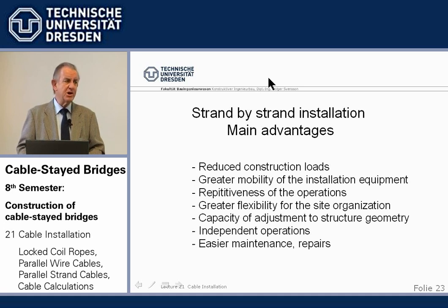And even in Germany, where all the early cable stay bridges used locked coil ropes, now we have the last two with parallel strand cables, which is Rheinbridge Wesel and the Strelasund Bridge to Rügen, which we have mentioned. So this is their sales talk. I'm just giving you as an example for the competition.